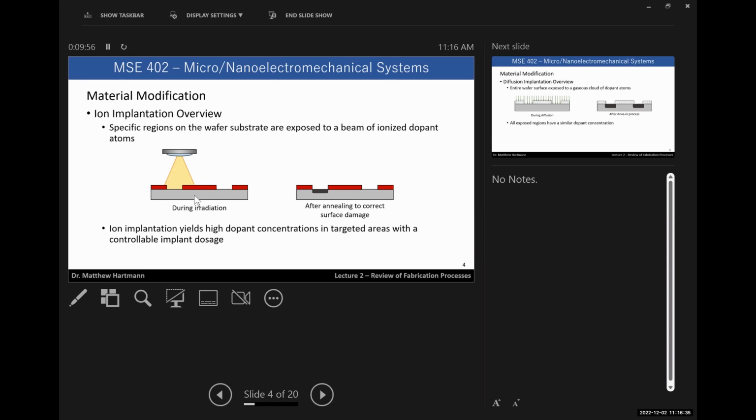During the irradiation process, we're going to have an extraordinarily thin layer of ions at the surface here that have been implanted, and they're going to have some mean depth dependent on their energy and all of that kind of stuff. The implantation process tends to actually deform the surface of the wafer and cause damage. Imagine if you were hitting golf balls at that brick wall as fast as you possibly could. Over time, it's going to make little chips and divots and things like that on the surface of the wafer.